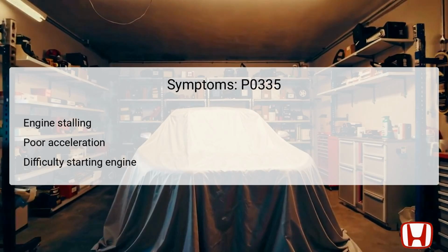The symptoms associated with DTC P0335 can significantly impact vehicle performance. One common sign is engine stalling, particularly during acceleration or when idling. This occurs because the engine control unit cannot accurately determine the crankshaft position, leading to improper timing for fuel injection and spark.